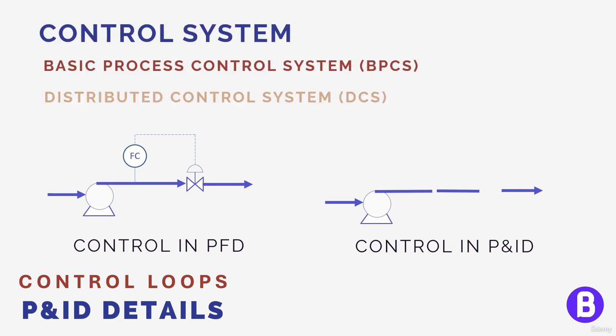This is commonly known as Distributed Control System, or in other words, DCS. So, in addition to the instrumentation device, which is the flow element here, it sends the reading in a signal to the flow controller itself. The controller can use the direct flow reading, or it can process this reading based on a custom calculation. Maybe it shall be added to another flow so that we can combine the flow of more than one stream or whatever the function we need.